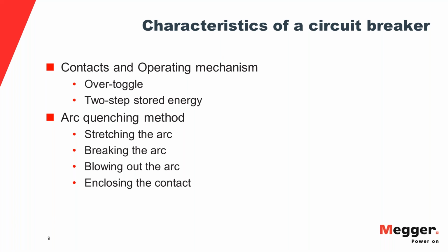Then there is the two-step stored energy mechanism, which is used in low voltage power circuit breakers, where there are separate springs for opening and closing of the breaker. So you can actually charge the spring for closing a breaker even before it has opened. What that does is give a reclosing ability to the breaker. So if the breaker opens in the case of a fault, it can be immediately reclosed remotely.